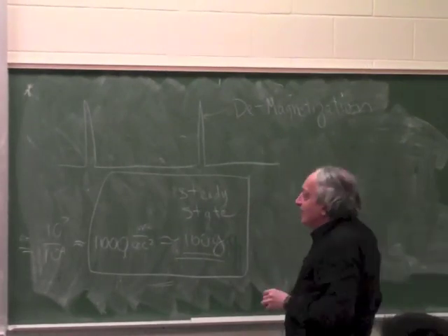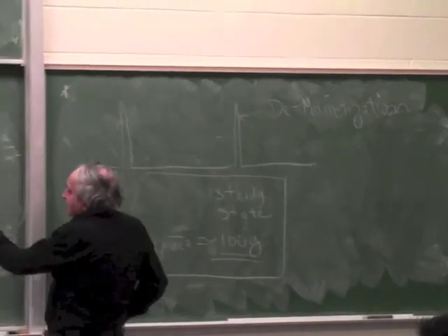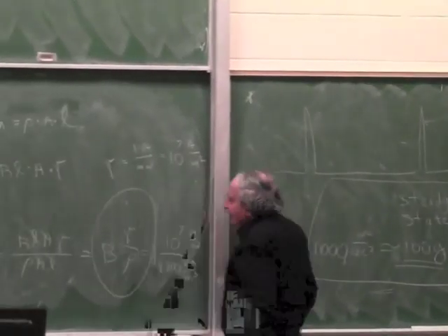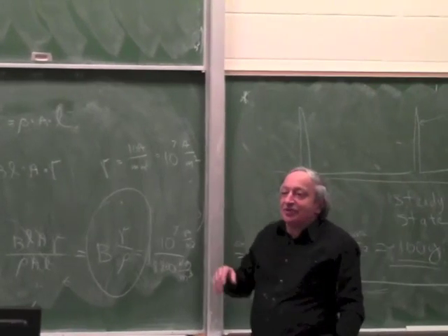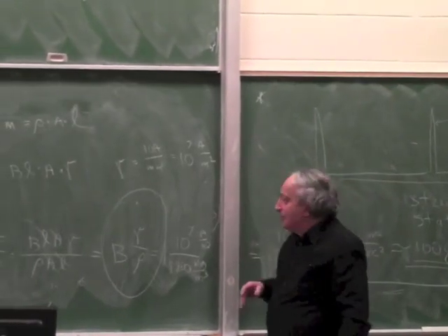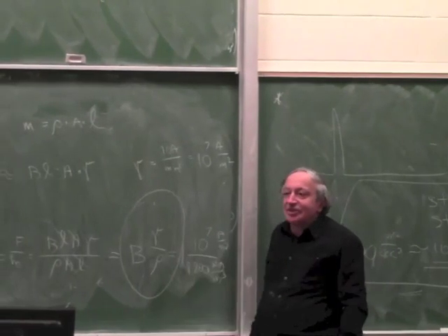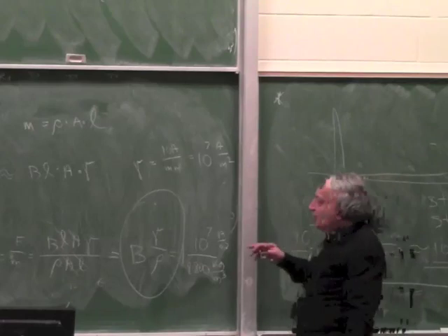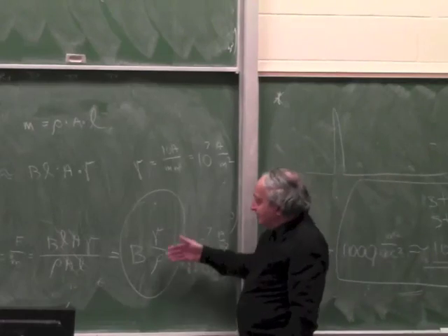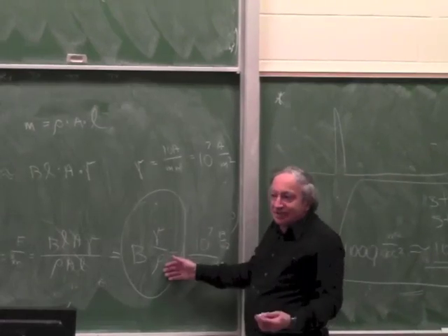Okay? So now when we look at this formula, we can start thinking maybe there is another degree of freedom. Instead of using copper, maybe we should use other materials. So what we're looking for is a material which has the best ratio of current density to density.